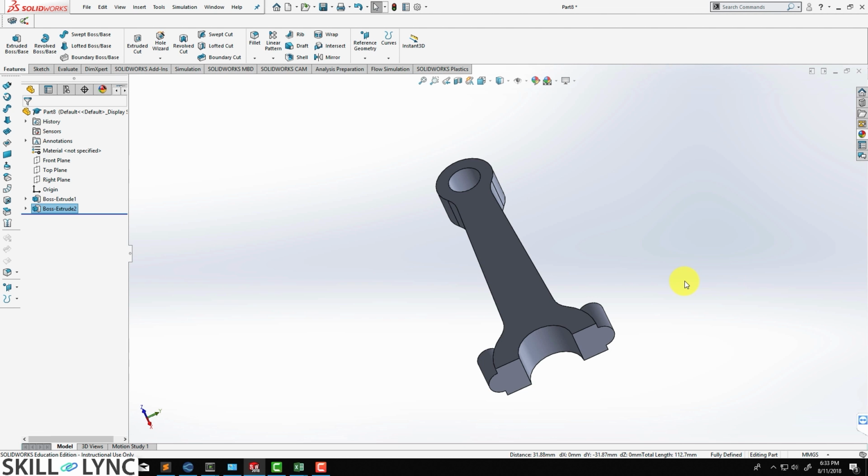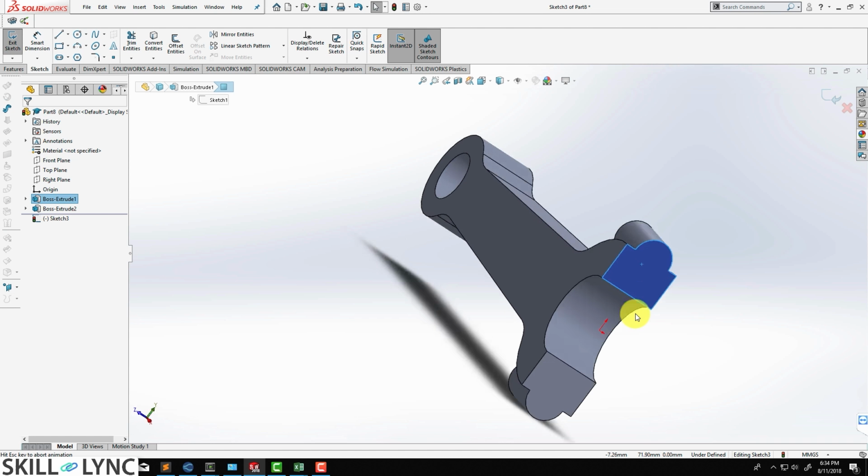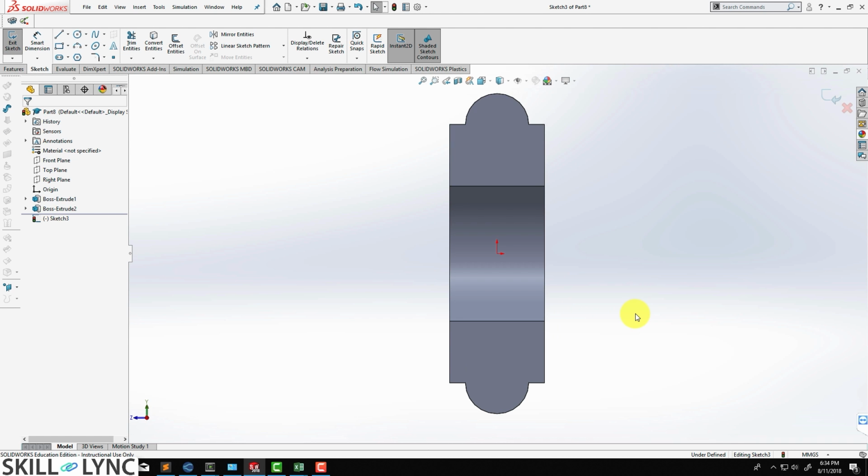Now we are going to be creating a groove cut on this particular face so that we can apply bolts later. So let's click on sketch in this particular plane, hit Ctrl 8 to view it in the right direction. And what we are going to do is fairly simple, right? So we are going to first select this particular sketch, and we're just going to click on show. Looks like it's there, but for some reason it's not visible.